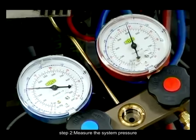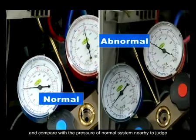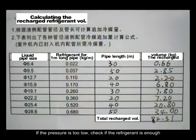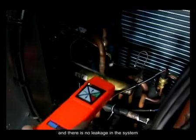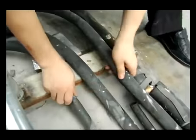Step 2. Measure the system pressure and compare with the pressure of normal system nearby to judge if the system pressure is too low or not. If the pressure is too low, check if the refrigerant is enough. Make sure the additional refrigerant is charged correctly and there is no leakage in the system. If it is normal, please go to the next step.